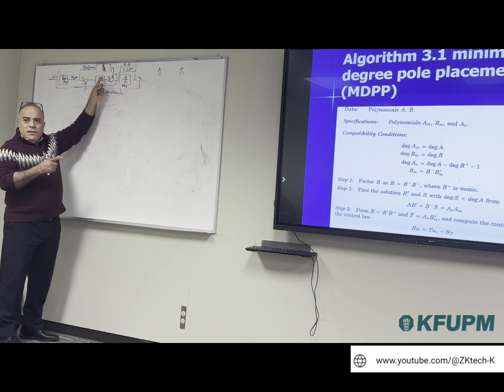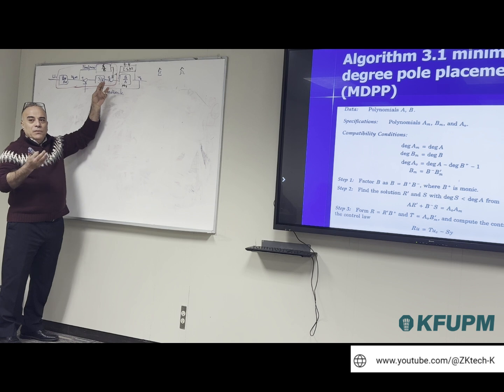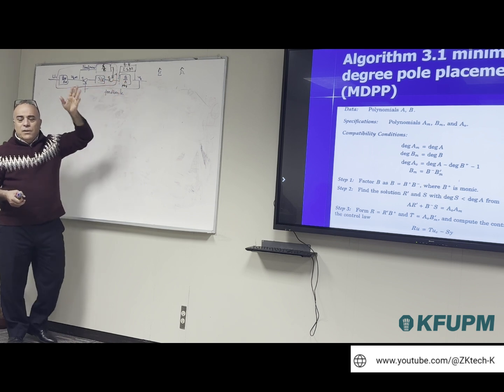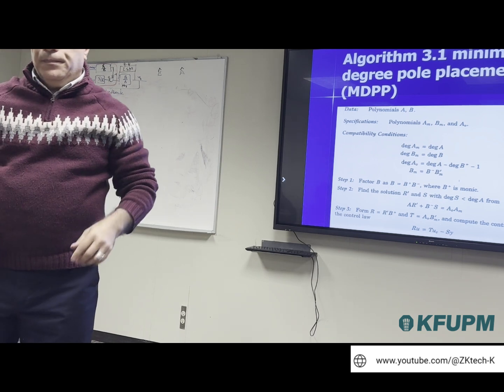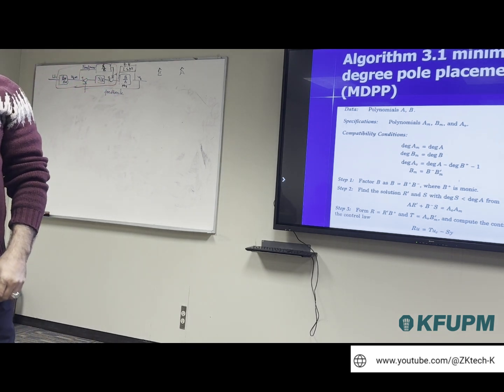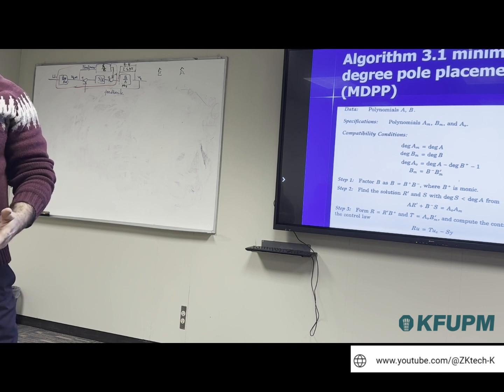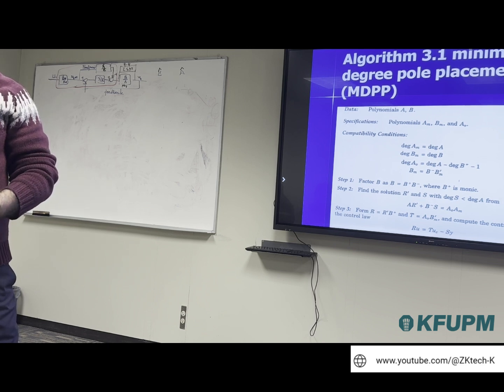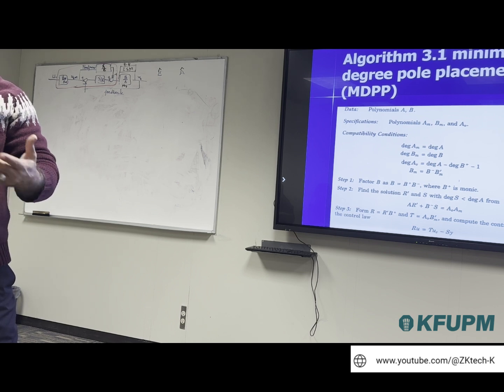I talked about this one time. I told you that most of the time we use the same clock, but in certain systems we don't identify all the time. So we have the control every 0.1 second, but the other one maybe after every 1 minute or 5 minutes or whatever, we do estimation. But during the transient period, you need to be able to estimate your values. You cannot wait 5 minutes with an estimate that is wrong, for example.